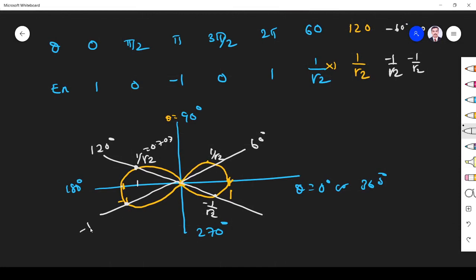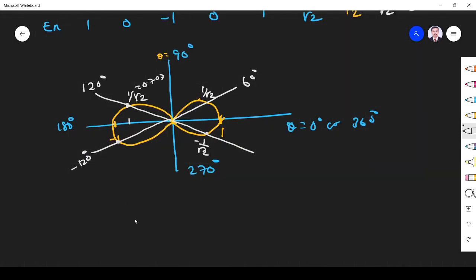So this is the radiation pattern due to an array of two point sources fed with the same current and opposite phase. You see, this is like an end-fire array pattern. If you feed two array antennas with the same amplitude and the same phase, it is a broadside array.